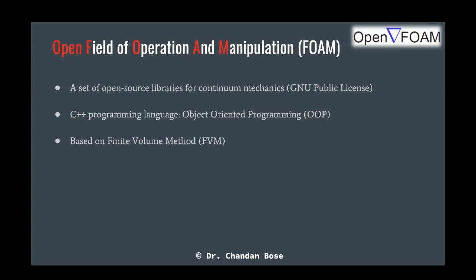All right, and the CFD methodology. What Professor Mittal was presenting, the in-house solver that he used, was based on which methodology? Finite element method, right? However, in OpenFOAM, the CFD principles or algorithms are written in the finite volume method. That means you discretize your governing equations using finite volume methodologies. All right. So what is the other methodology apart from it in CFD that you learn in your CFD course? It is the finite difference method, right?